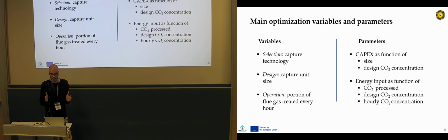Then we have some parameters. We have the capex of the capture unit as a function of the size and as a function of the design CO2 concentration. We have the energy input to capture the CO2 as a function of, of course, how much CO2 we are processing, the design CO2 concentration, and also the hourly CO2 concentration to account for these off-design conditions.